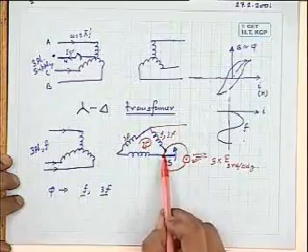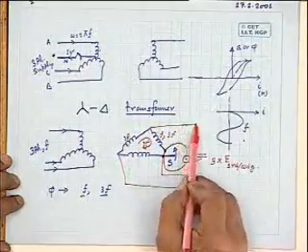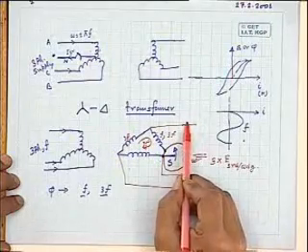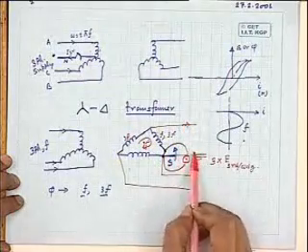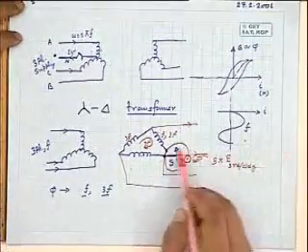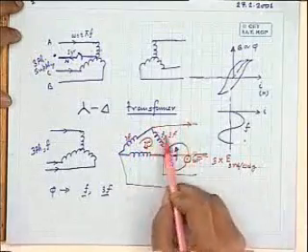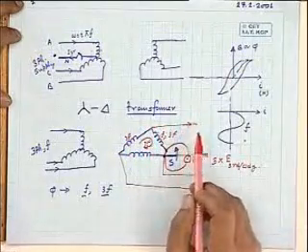This third harmonic current, after you have completed the delta by closing that switch, can there exist any third harmonic current here in these lines? Not possible. In a 3-phase 3-wire system, no third harmonic current can exist. So this current will only circulate here. There will be nothing reflected in the lines here.